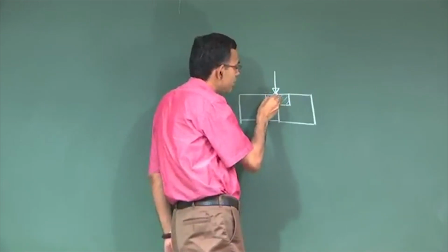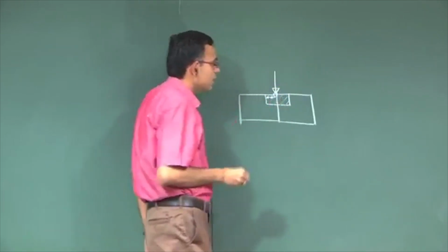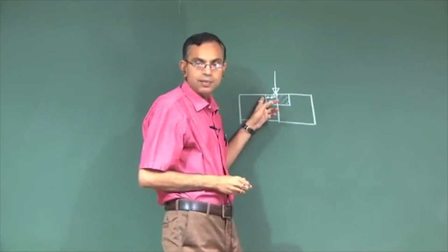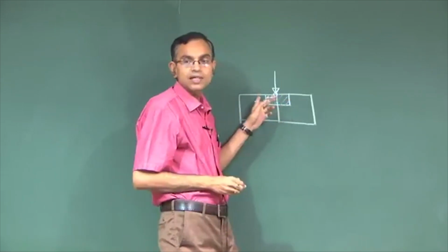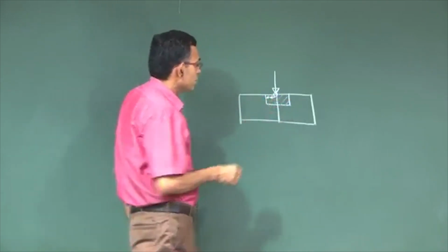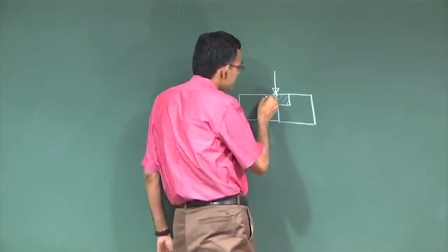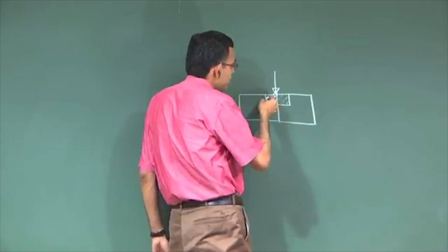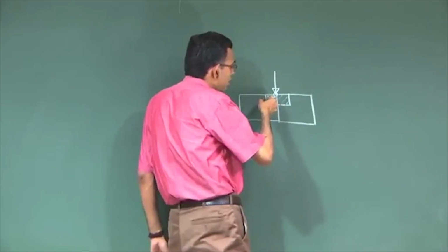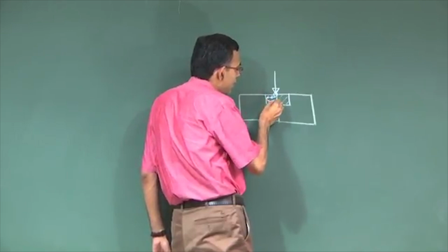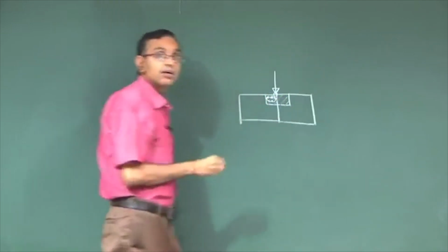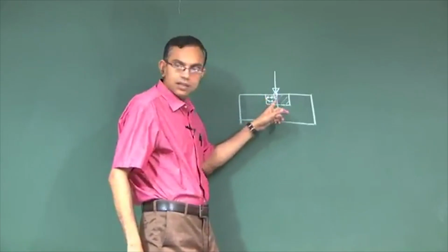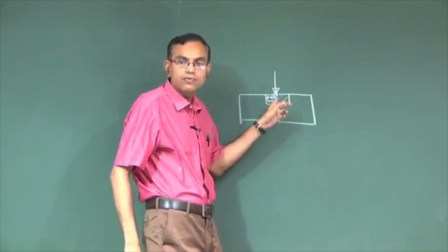Therefore there will be a force on the fluid in the molten region from the higher temperature to lower temperature, that means from lower surface tension to higher surface tension. Once this is created, this flow will eventually come down by gravity effect and will come up by buoyancy. So a nice circulation loop will be created to make sure that there is continuity in the flow.